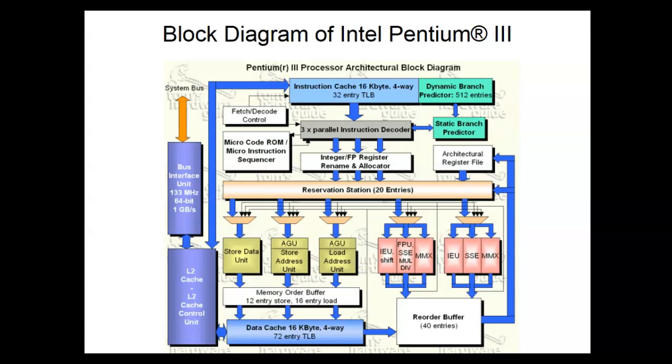So this is the heat sink. And it's got a thermal paste. Usually it's just a pad, but the problem is these surfaces can't be perfect. So all the little gaps that might exist, you make a good connection with a thermal transfer paste. Here's the process right here.